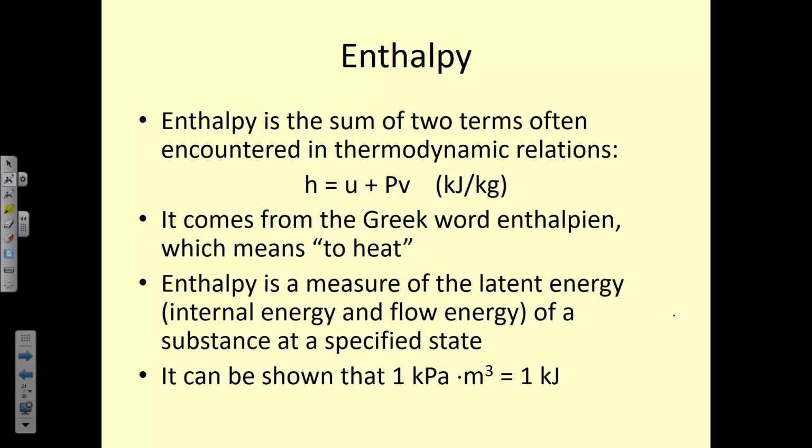And then in many cases, when we have an energy term, for example, P times V is kilopascals times meters cubed per kilogram. So kilojoules per kilogram, we can do it either way. That internal energy is always given to us in terms of kilojoules or kilojoules per kilogram, but this kilopascal times a meter cubed is an equivalent energy term. So again, going back to the unity conversion ratio, sometimes you'll encounter that kilopascal times a meter cubed or meter cubed per kilogram as you're working out your units. It's important to remember that that's equivalent to kilojoules.